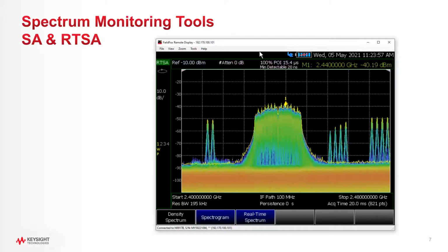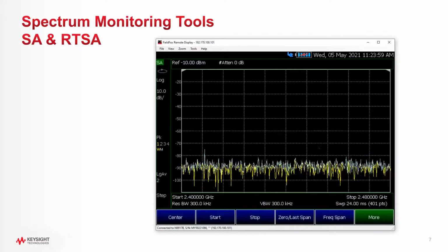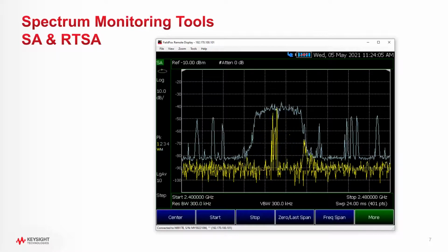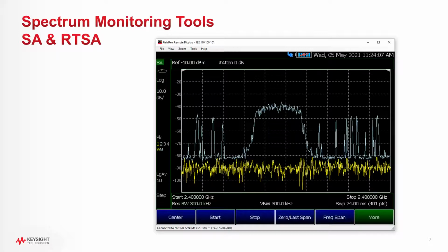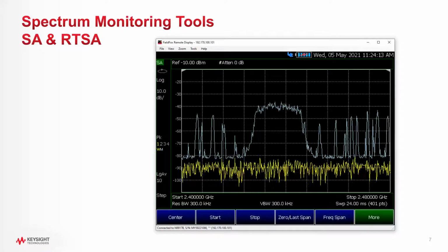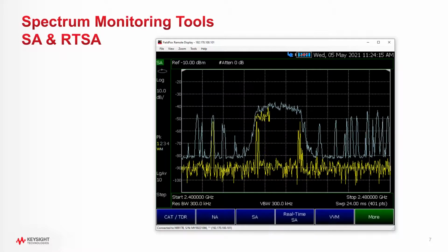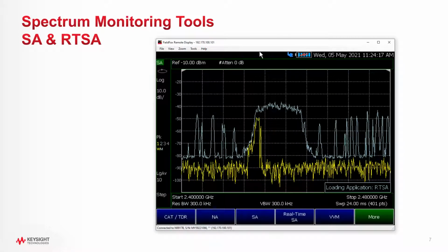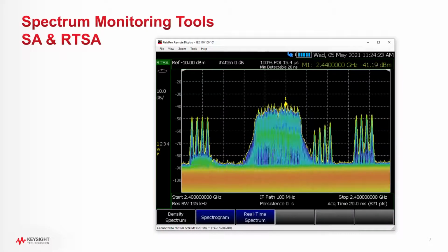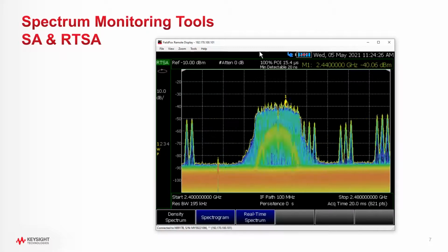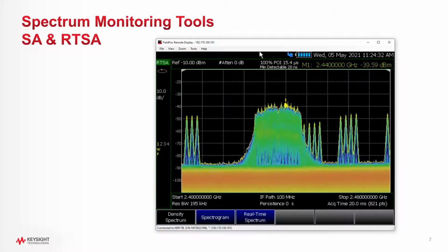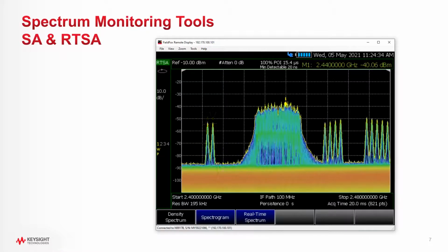So for instance, I'm going to go back real quick to the spectrum analyzer. One of the things that you see in that big center section is the yellow spectrum pop up and down in little skinny bursts, and it ultimately painted in that blue. But the reality is that's not how the Wi-Fi is working. The Wi-Fi is actually bursting on and off. And so you can see now in the center that it is there all the time, and you can see another Wi-Fi over on the left that comes and goes. But you notice how it's not little fragments. It's either all there or it's not.